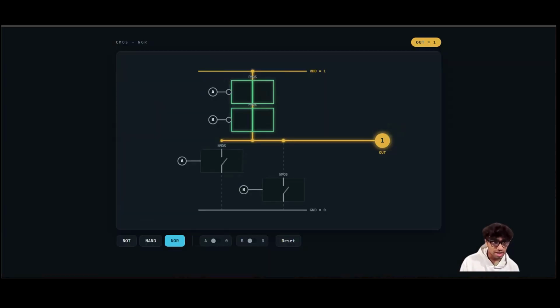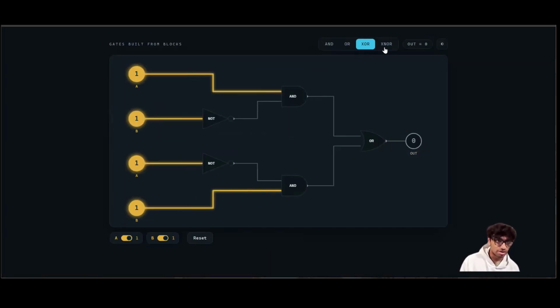And to make an XOR and XNOR, they're a little more complicated and they're kind of composite. To get XOR, you need 5 gates. We can even count the transistors here, and I think it's going to come out to be 4 plus 16, like 22 transistors total for this full circuit. I think you can make it with a more complex architecture and some triple input gates. But my point being, it does look more complicated, but it still just comes down to MOSFETs at its core. It's still just transistors under the hood.